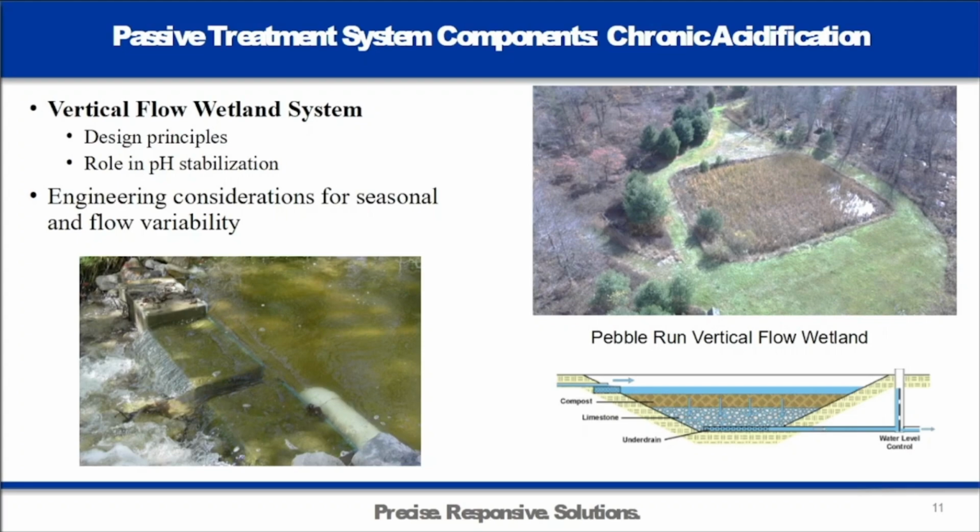The intake systems on these are what's a little bit interesting. They build a check dam across the stream to get a water level control here. And what they had done at the time was put a pipe on the backside of it that goes to an agri-drain with an orifice. We want to treat 100 gallons per minute.